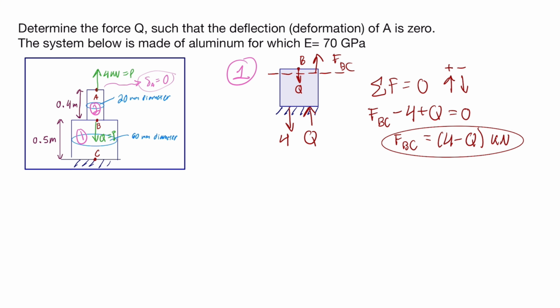So we will use this force to calculate the deformation of this segment. So the equation that we will be using is this equation, which is the deformation is equal to the force times the length over the area times the modulus of elasticity. So we will plug in the numbers that we know to solve for this.